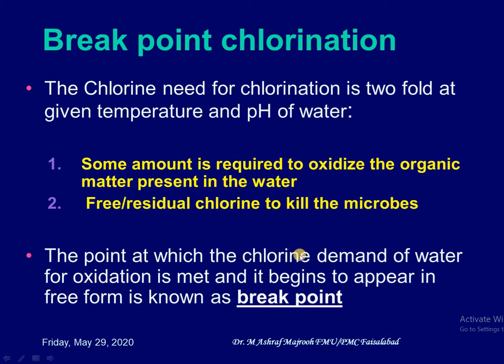The point at which the chlorine demand of the water for oxidation is met and chlorine begins to appear in the free form is known as breakpoint chlorination. And this is the point that provides the free residual chlorine for bactericidal action.